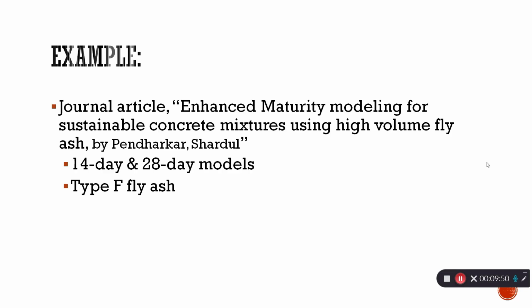A 14-day new maturity strength prediction was examined against the traditional maturity modeling suggested by ASTM C1074. The 14-day pull-out force versus compressive strength showed small improvements for the 35% of type F fly ash and the 50% of type F fly ash mixtures. The mixture with 35% of type C fly ash had better estimates with the 28-day correlations. The 35% of type C fly ash also shows us that the 14-day maturity models underpredict the in-place compressive strength.